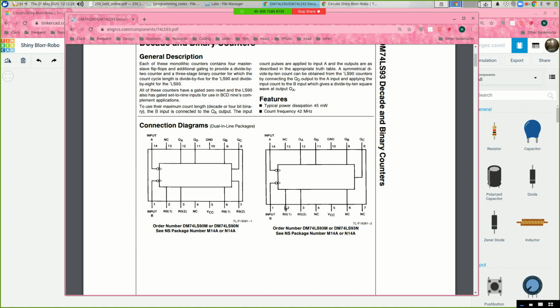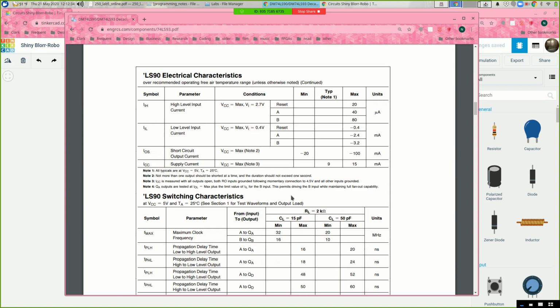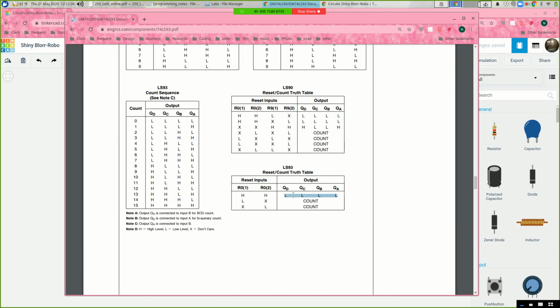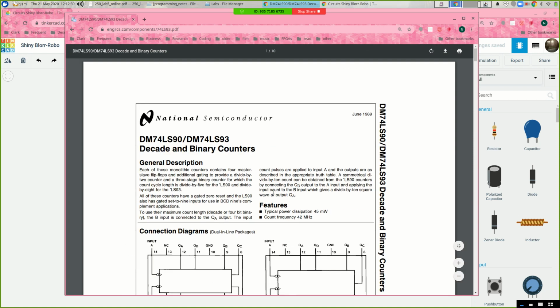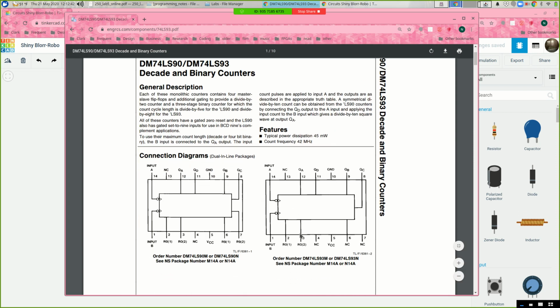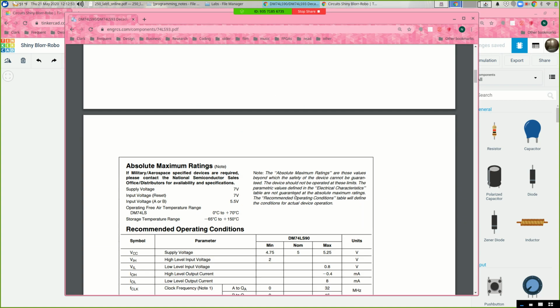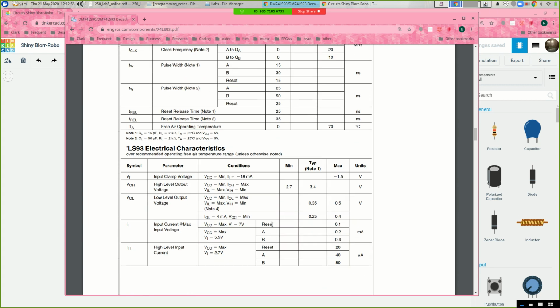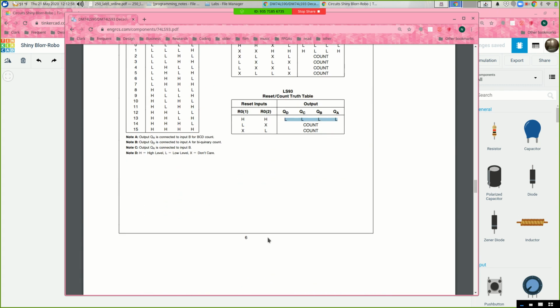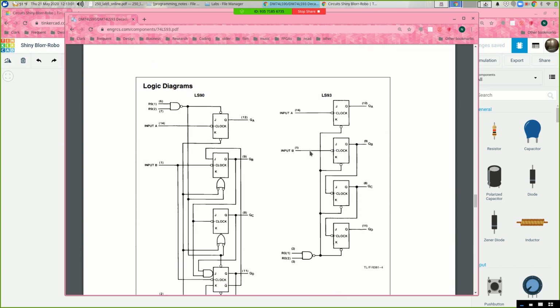And to start, we're going to take pins 2 and 3, and we're going to drag those low. We're going to connect them to ground, and then we'll figure out how to make this thing reset. So we want both of these to be low. That's 2 and 3. So connect those together, and we'll pull that to ground. And then remember the trick that I told you? The one thing you need to know to definitely make this work is connect pin 12 to pin 1 and then use 14 as your clock input. So let's connect 12 to 1.